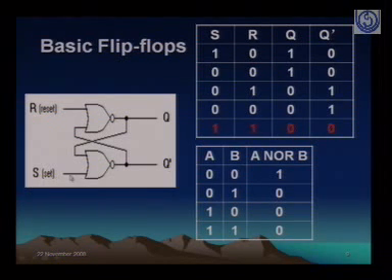Because one of the inputs is 1, automatically this Q prime is going to result in 0, as per the truth table over here. At the same time, what you see here is this particular output, the Q prime output, which is now 0. What is the reset value at this point of time? It is shown over here, it is 0. So after the propagation delay, what is the value of Q prime? It has to be 0, because from the NOR gate it got converted to 0.